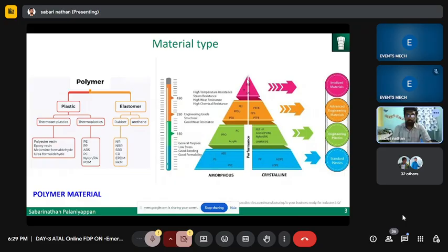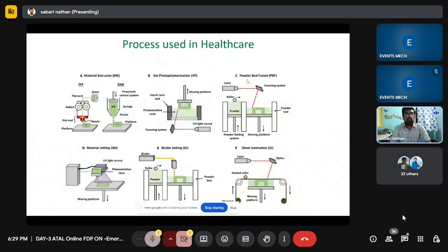Okay. So I have already discussed these applications. The first one is material extrusion, and I have already explained fused filament fabrication. The next one is direct ink writing. The difference between FFF and direct ink writing is that in FFF the material is extruded using a heat source. In direct ink writing, a pneumatic control system based on pressure deposits the material on the platform. After that, the curing depends on the method of curing.